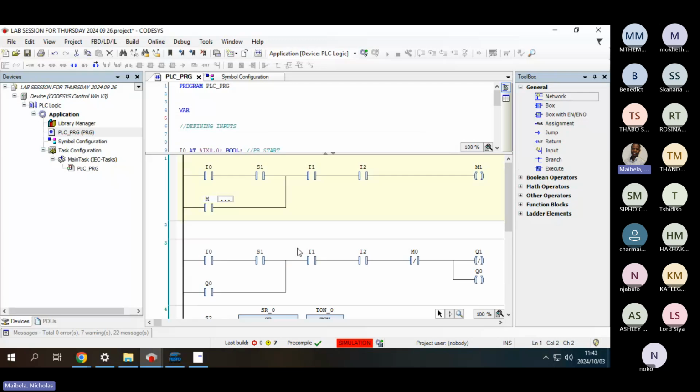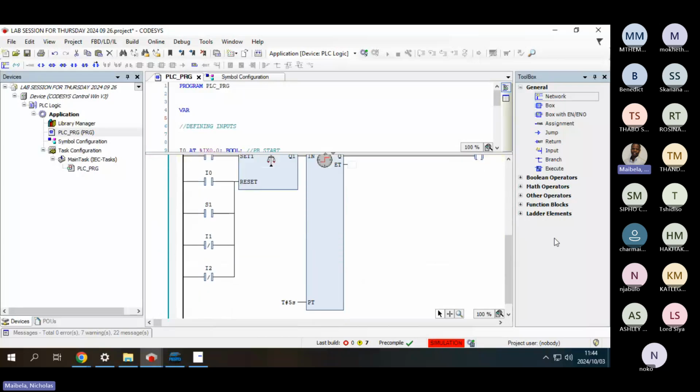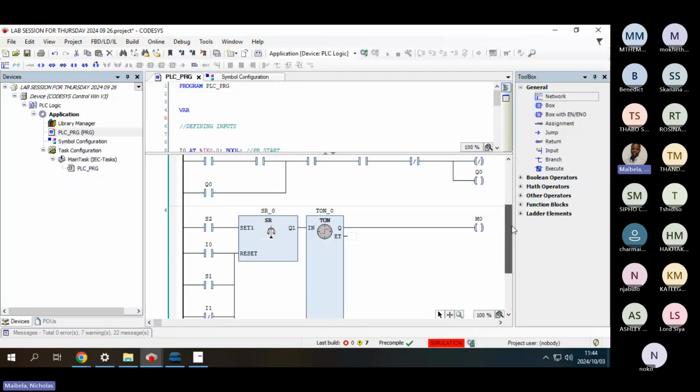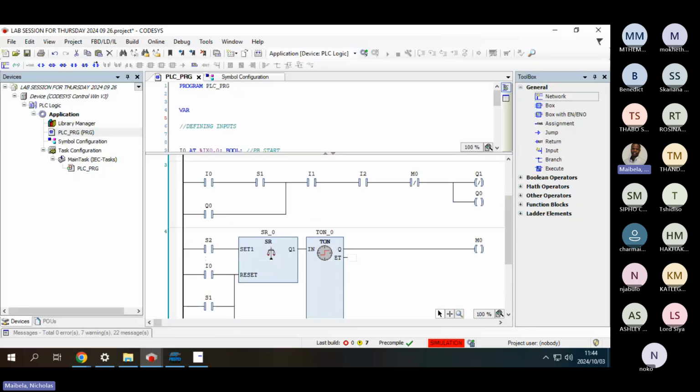And then also here you latch that, then you can click enter. So as you can see, your output here is latched, meaning there's continuous current flowing through M1. Now this very same M1, you're gonna use it for setting your time. Remember, this exercise is a continuous run of your circuit. Your circuit will go forward and back, forward and back, up until you press a stop button.